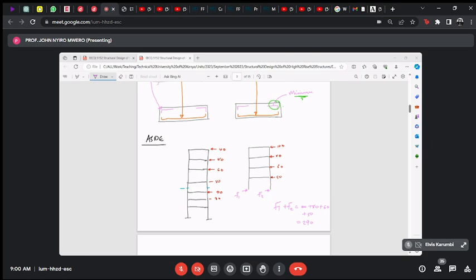So thank you. Allow me to stop at this point now. Yes, Mutero. When it comes to the shear wall, are they designed to carry any lateral, not lateral, but axial loads? Yes. You see, because the shear wall is part of the building, it is tied to it. How do I explain this easily? The shear wall is actually a column that is optimized to carry lateral load. That's where we started from, if you can remember.